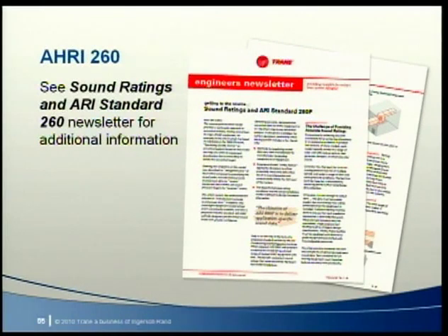Prior to the introduction of Standard 260, a common practice was to test the fan in a standalone configuration and then apply calculated unit effects. Depending upon the fan and the unit interaction, this method could be off by more than 10 dB, even for simple unit configurations. When you compare sound data from different manufacturers, be sure that they all have sound data taken in accordance with Standard 260 so that you are comparing apples to apples. Refer to our Engineers Newsletter on sound ratings for additional information.